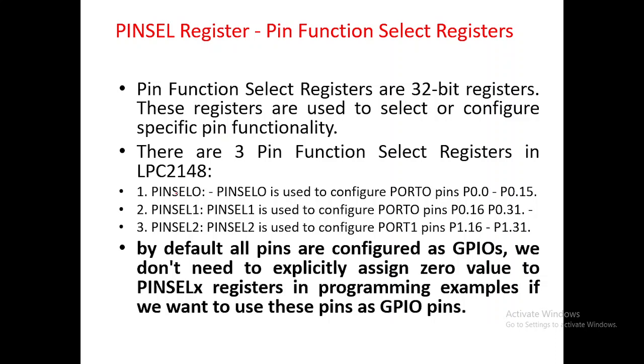Pin select register 0 is used to configure port 0 pins 0 to 15. Then pin select 1 register is used to configure port 0 pins 16 to 31, and pin select 2 register is used to configure port 1 pins 16 to 31.